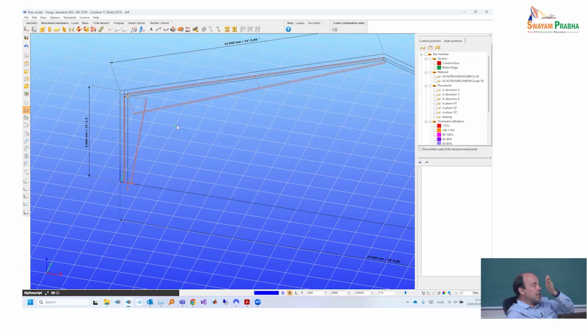And in addition, at every position where we have a flange brace, we will add another lateral support to the inside flange, okay? So at some positions, we will have support on the external flange only, and at some locations, we will have two supports, one to the external and one to the internal, okay? This is very important. If you don't make these supports, then probably even the first buckling calculation will fail, because the whole structure can fall down, or even if it runs, its critical load multiplier will be 0.0000000, neglect, so nothing wrong. Okay, that's not what we need for the slenderness.